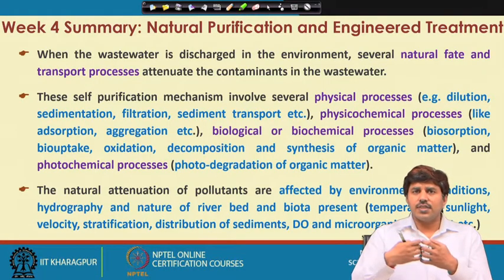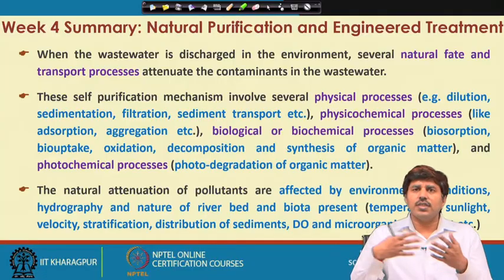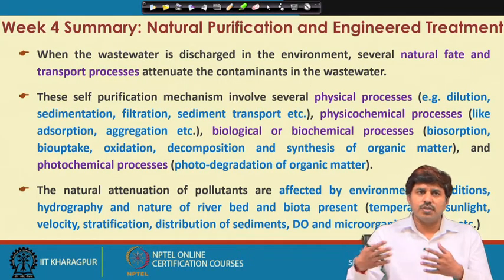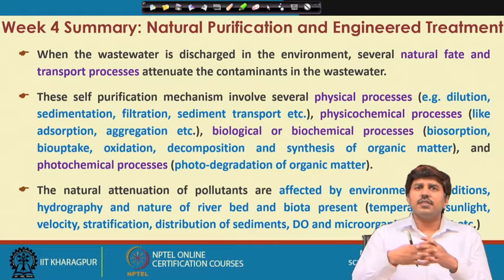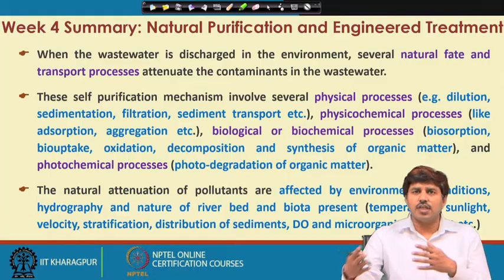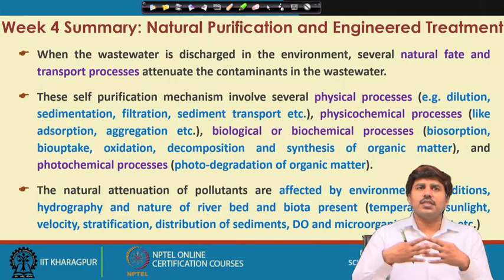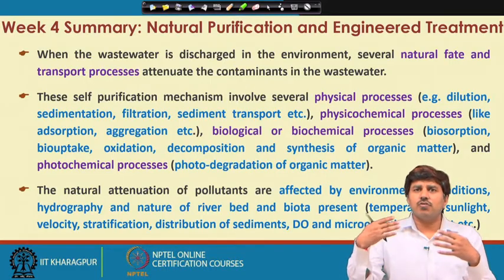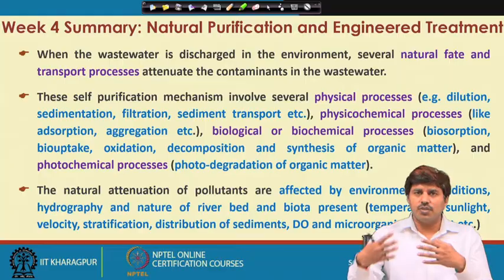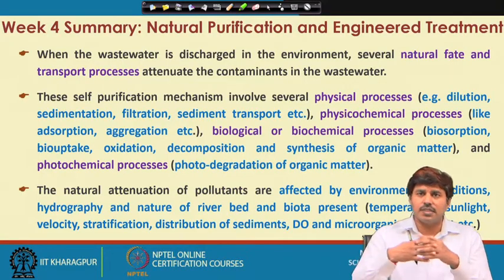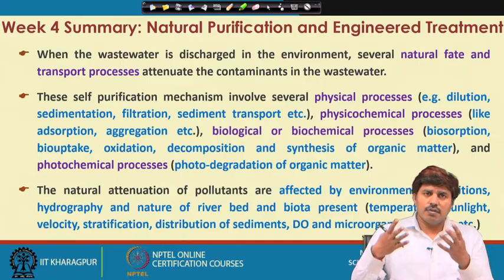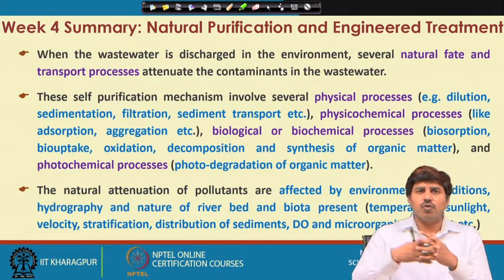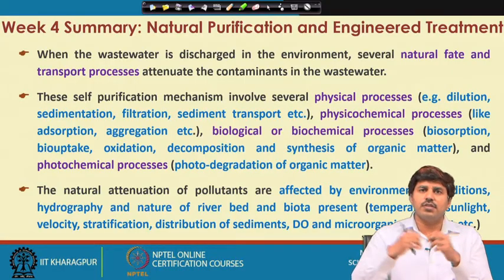This leads to the self purification of the water when it is particularly disposed of in streams. These self purification mechanisms involve several physical processes like dilution, sedimentation, filtration or sediment transport, various physicochemical processes like adsorption, aggregation, etc., and various biological or biochemical processes. So, biosorption, biouptake, oxidation, decomposition and synthesis of various organic matters, and to some extent, particularly in exposed water systems, photochemical processes like photodegradation of organic matter may also have some contribution.